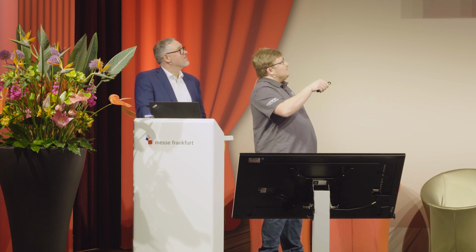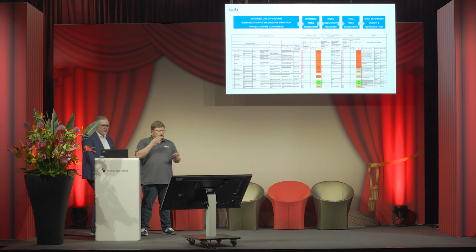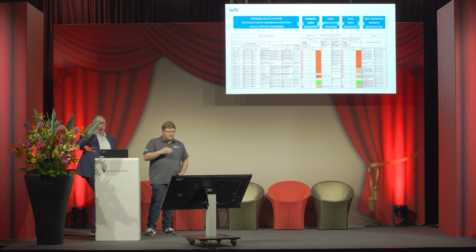So the first step, which is dealing with the risk analysis, let's say there are 5 main steps during the risk analysis. The first one will be basically a complete list of all the different hazardous situations that the users or all the different people who are working with the control system or implementing the control system and also the electromechanical devices will meet. So basically that's everything that can occur during the montage, the commissioning, the normal use, during maintenances, and so on. So all the different hazards are listed, all the different causes, consequences, and so on.